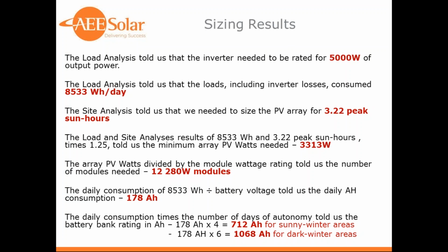Another thing I'll point out is that generally when you do this analysis, there's a lot of guesswork involved. You're guessing how many hours a particular load is going to run. And from my experience, at least, once people establish a system, they tend to add loads over time. So you want to design the system to be expandable, or at least even have it larger than the original design states to allow them some room for expansion, to maybe add a freezer, for instance, that they don't have, or some other kind of load.